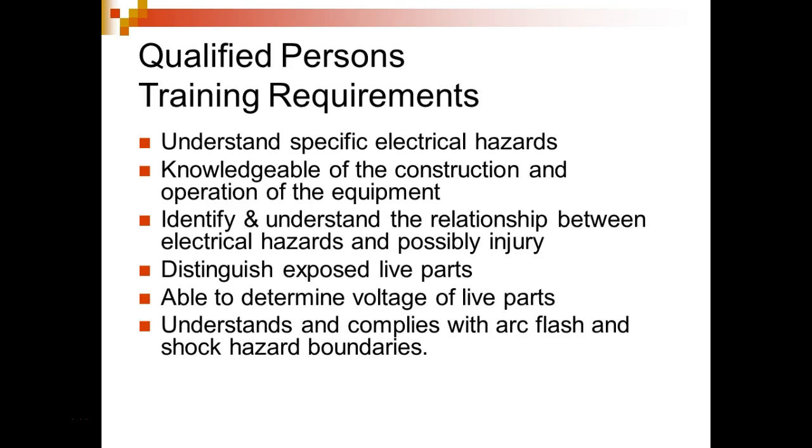Because meters blow up on them. They will literally blow up on them because they're sealed units. And if you overdo them, you got expanding heat, it starts short circuiting inside the meter, and it's got no place to go. So what will it do? It'll blow up on them. And then you create arcs, and then you got big problems.